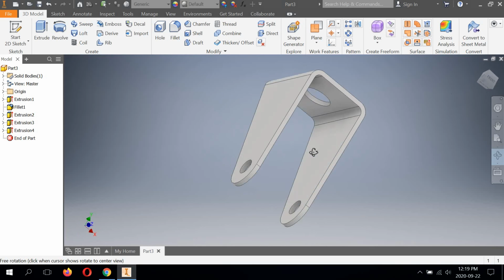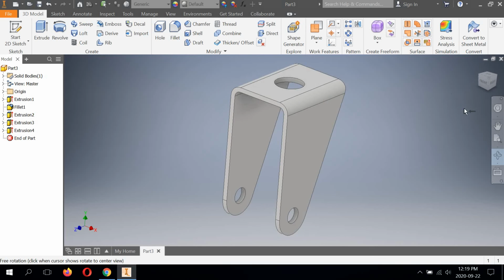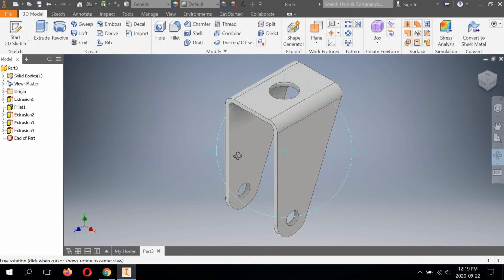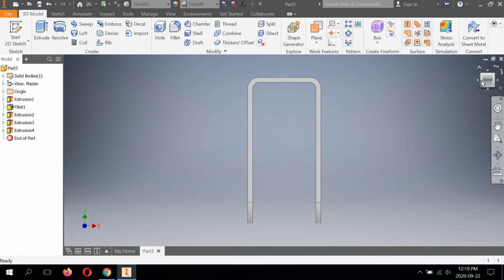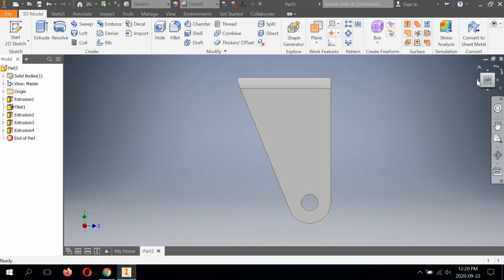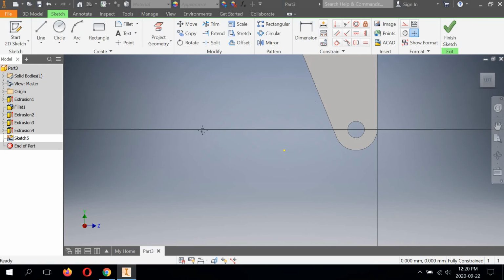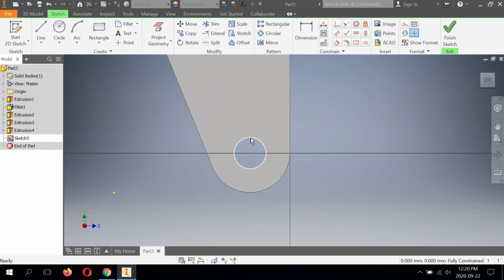We have one last thing to do, which can be a bit tricky now, is the keyway. This allows the rib on the shaft to insert and lock into the bracket. So we're just going to go to our left side view here, hit 2D sketch on this surface or face.